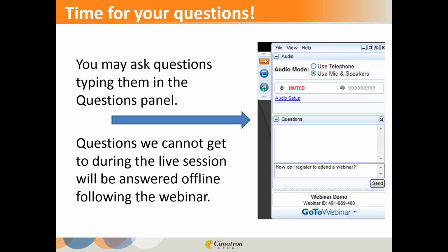Because at that point, metal's going to act like metal. So whether you've got it drawn in or not drawn in, if you draw it in, you've got a pretty good idea what the actual true metal shape is going to be like. Right. Versus the one where you're just kind of on the fly saying, yeah, I want to throw a draw bead in here, what's going to happen?